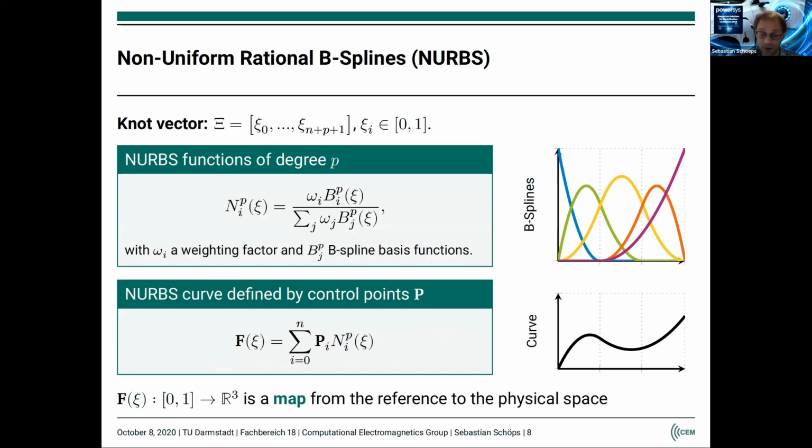Splines are very expressive. For example, you can represent circles exactly, which is very relevant also for electrical machines. I said I do not want to bother you too much with the mathematical details. So I talked about splines, B-splines to be precise, and even more precisely NURBS, non-uniform rational B-splines, which, as this formula says, are essentially splines divided by splines. This is necessary because only those can represent a circle exactly. But anyway, keep in your mind a picture like this: you have piecewise polynomials, you combine them, and they give you a beautiful shape, and eventually even a circle.